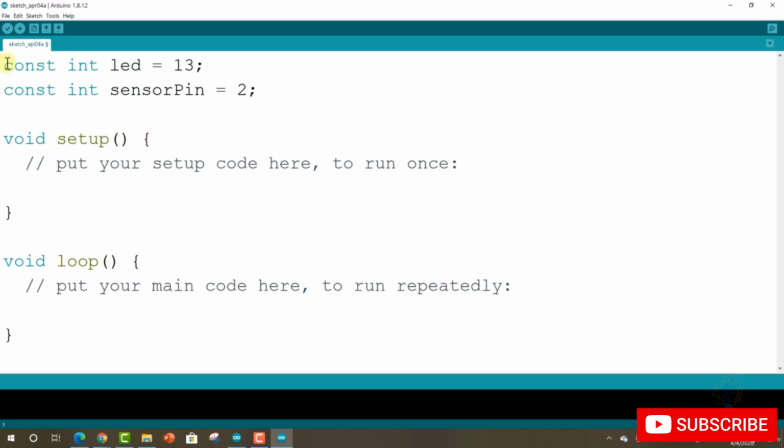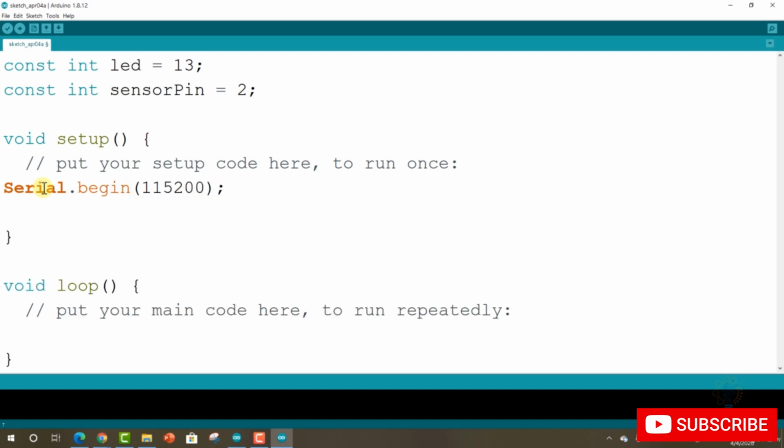Now let's go to the void setup. First, we need to start the serial communication at a baud rate. We usually use 9600. You can use 115,200 for faster processing.